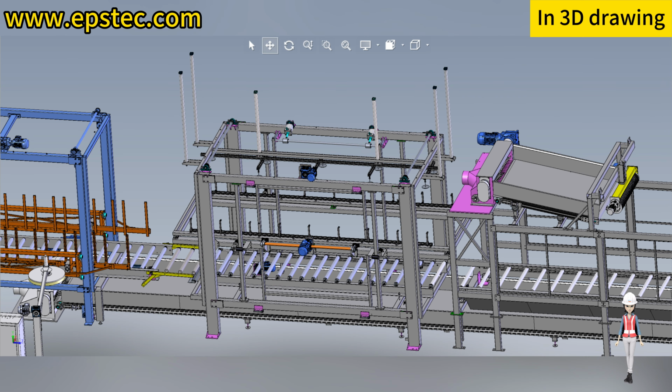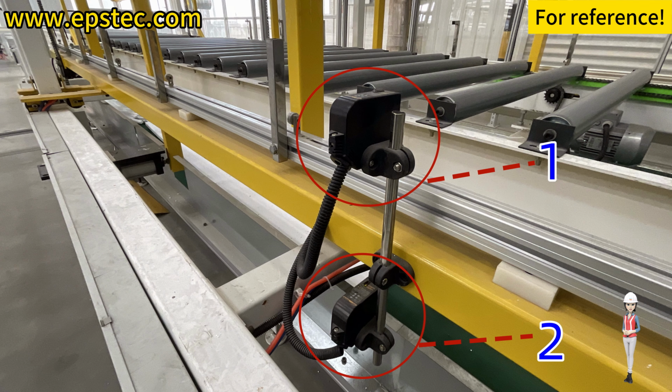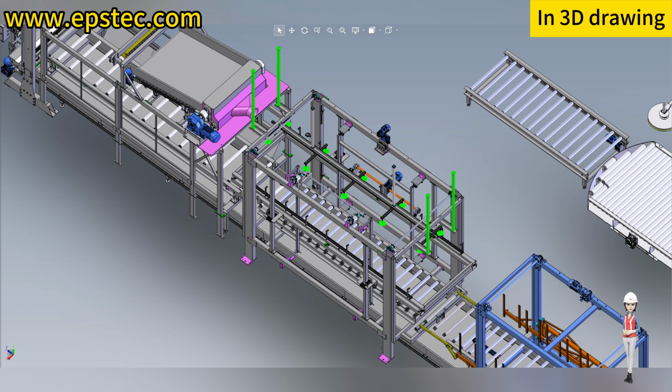At this time, the cutting wheel starts heating, the third phase cooling fan starts, and the cross-cutting frame rises at the set vibration cutting speed to cut the EPS block in the third phase cutting section. When the cross-cutting frame rises to the position of the first photoelectric sensor, the signal is lost, and at this time, the third phase top press plate cylinder and the waste block cylinder retract.